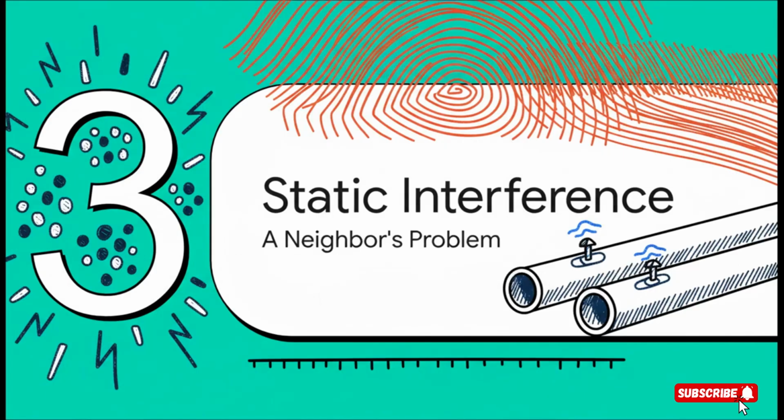Now, moving on from those jumpy dynamic currents, we have static interference. This is a much more stable, constant problem. The source isn't turning on and off. Nine times out of 10, this is a case of good fences make good neighbors, because it's usually another company's cathodic protection system bleeding over and affecting yours.